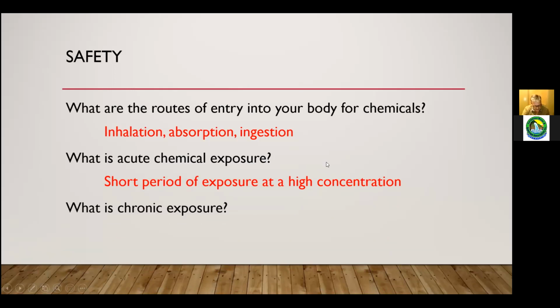And what is chronic exposure? That's the extended period of exposure at a low concentration. Many areas of this facility, especially basements, maybe dewatering centrifuge activities, might have low levels of H2S or other items kicking around in there, and they would be chronic exposure because you're working in those areas all the time and potentially a low exposure.